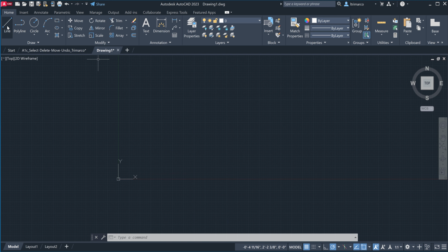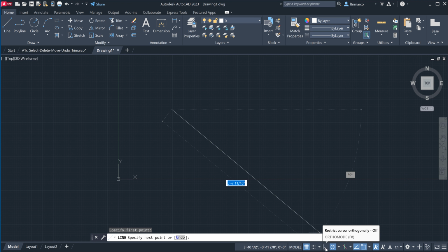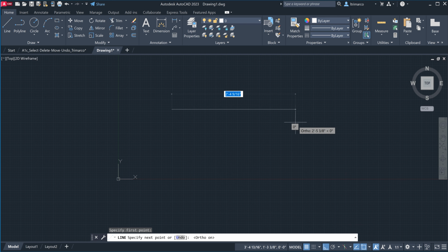So again, I'm going to get back to drawing a line. Snapping a point, I do need this to be either a horizontal line or a vertical line, so I am going to turn on what's called ortho mode, which you can turn on by hitting your F8 key. Now you can see I'm locked in horizontally along X, or locked in vertically along Y. I'm going to draw a horizontal line to begin, and I'm going to make it 6 foot 3. Now notice how I'm entering a coordinate. We'll get into this again this week in our week 2 session, but basically your first number is always going to be feet, of course.